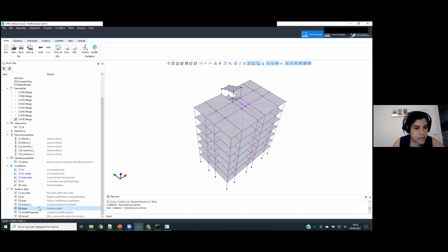Okay, so in this case, you did the analysis of the load you applied, then the eigenvalues, then the model, and then we record again. Yeah, I mean, this can also be useful if you're doing a nonlinear model that will affect your model properties. If you put the eigen command afterwards, this effect will be recorded. Otherwise, if you put it before, it will not be recorded.